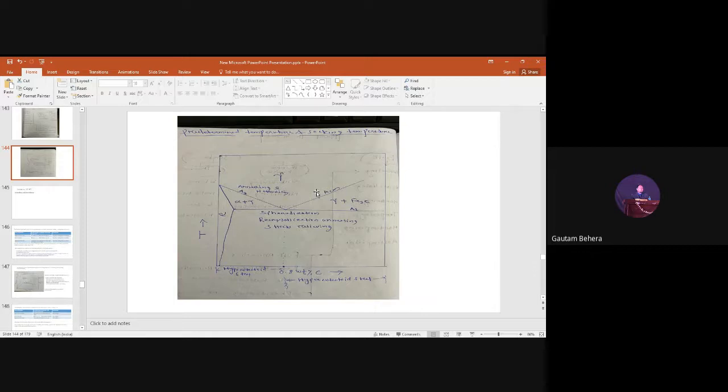That is one part. Another part is, if cementite is only present along the grain boundaries, that should be discontinuous. It should not be a continuous network. That is also fine. Now we have no problem much. So the best one is the spherical form of cementite, very good. It will provide good toughness and ductility also, right?